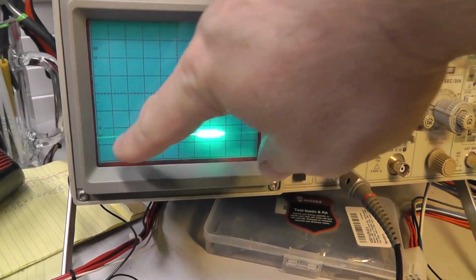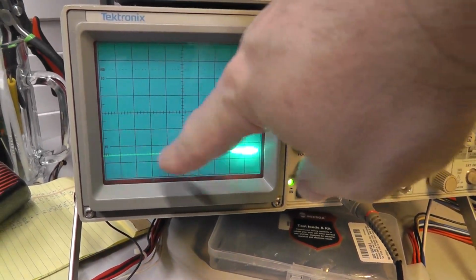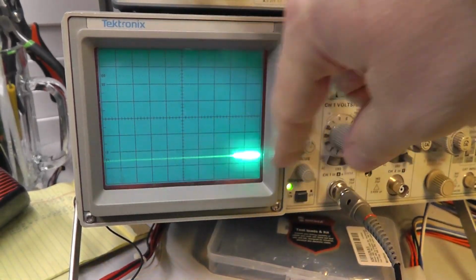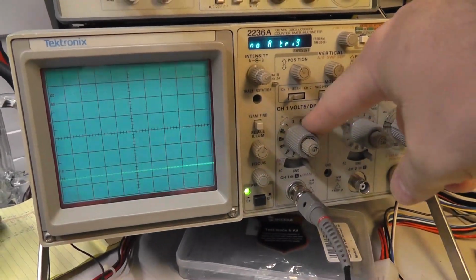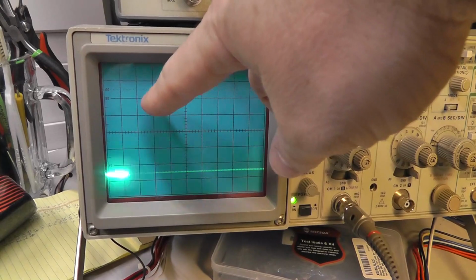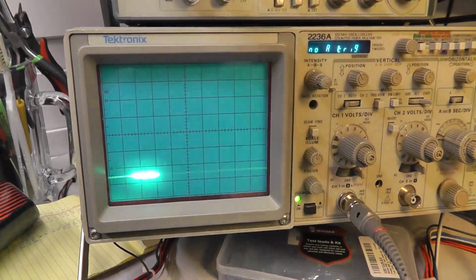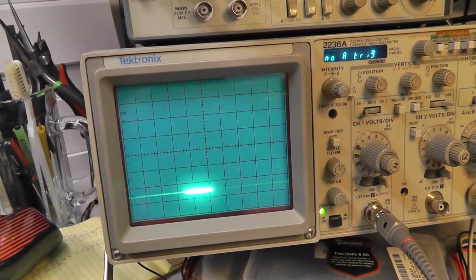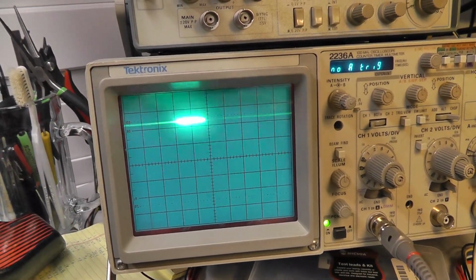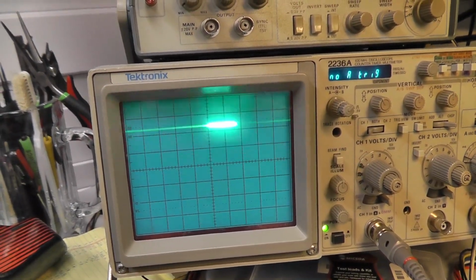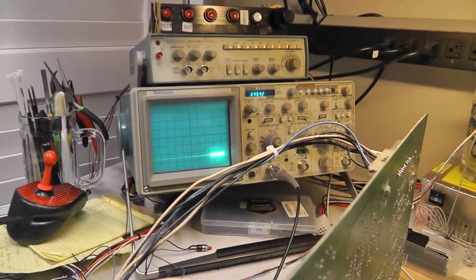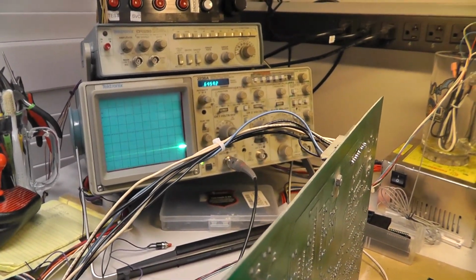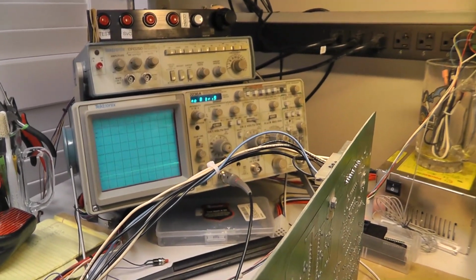By the way, I adjusted my meter because on my graticules, I never knew this. It says 0% way down here. And so if I have my volts per division correctly, I'm using a 10 times probe, 5 volts should go all the way up to 100%. So if I come to like a 5 volt, you see it right there, almost 100%. So 0% is ground. So I basically adjusted my graticule.